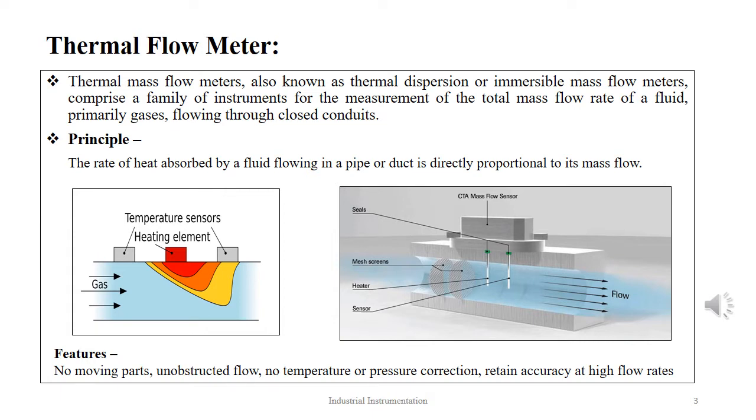Thermal flowmeters measure mass flow rate by means of measuring the heat conducted from a heated surface to the flowing fluid. Relying on the principle that a fluid flowing past a heated temperature sensor removes a known quantity of heat as it passes, thermal flowmeters measure either how much electrical power is required to maintain the temperature of the heated sensor or the temperature difference between the heated sensors and the flow stream. Either of those values is directly proportional to the mass flow rate.